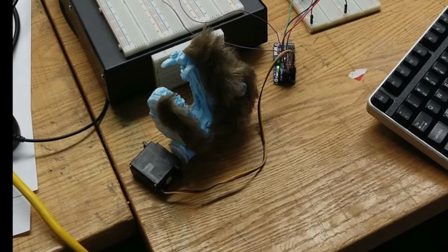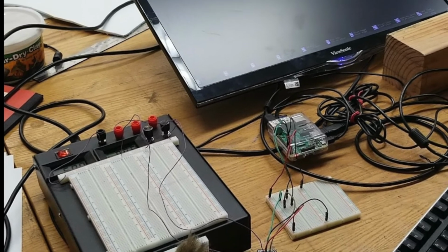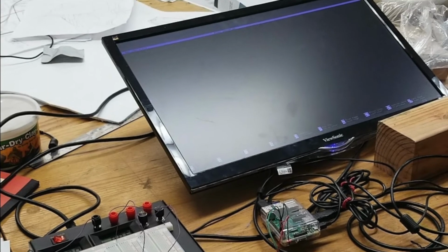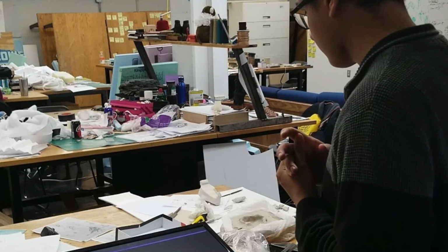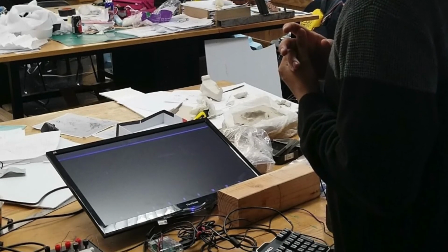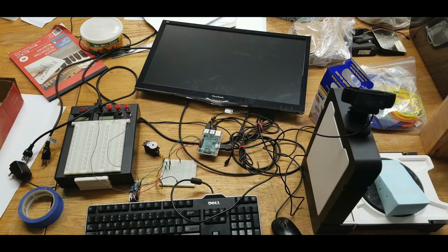We decided to use a Raspberry Pi to make our wolf head autonomous. We already had the prior hardware to use stepper motors to actually make the model move, including a servo board control made by Adafruit and a variable voltage gate that actually powered our servos. We used Python to make the facial recognition system. We used a library called OpenCV, which scanned for faces and images. And we used a webcam to get those images from the surroundings, and then simply used the Raspberry Pi to linearly interpolate between angles to point our servo towards the face.